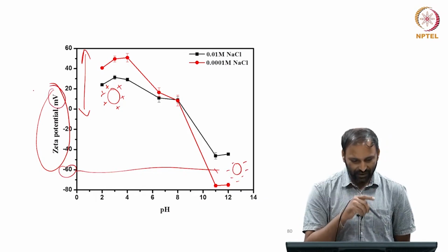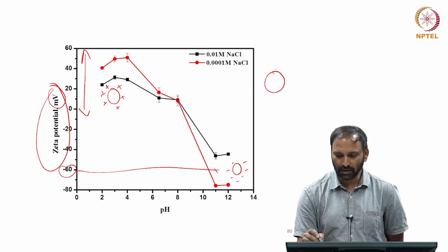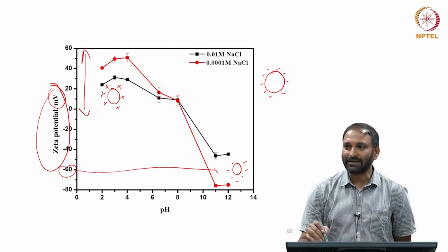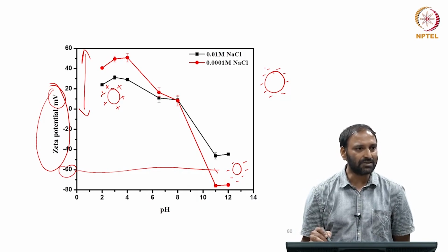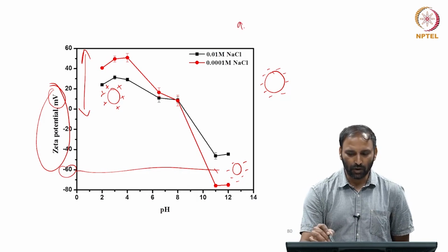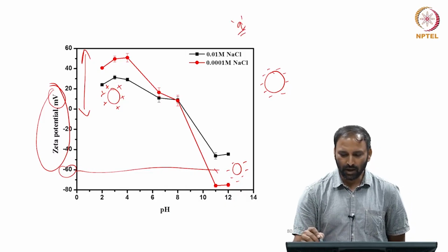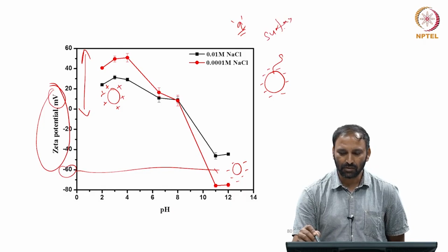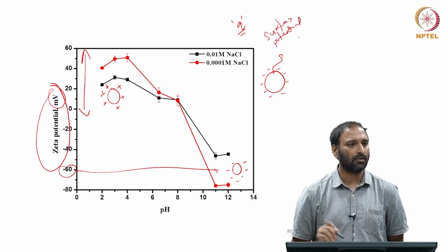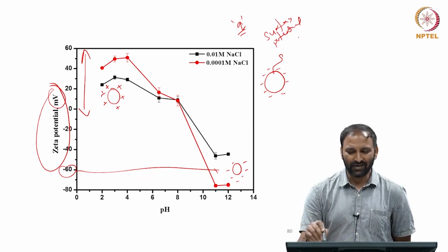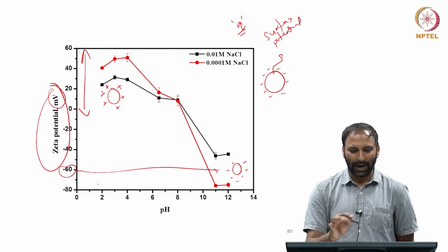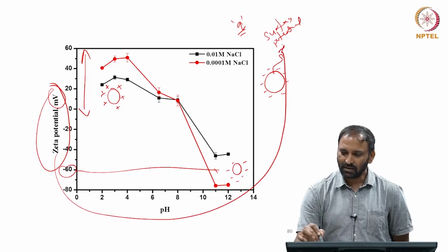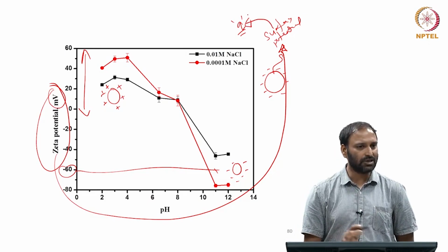We will learn that whenever you are working with charged particles in a fluid, the mathematical treatment becomes much simpler if you do not work with charge, but with a quantity called surface potential. Again, we will define what surface potential is in a while. This zeta potential can, for all practical purposes, be taken as the surface potential, and that is somehow related to q. Let us put it this way at this point.